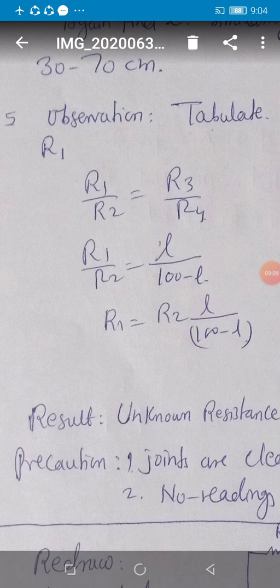Students, some precautions are always taken in an electrical experiment. The current should be switched on only when the readings are taken. And the joints where the wires are joined, any connection, should be thoroughly cleaned, student, because as you know, copper forms oxide, and copper oxide has its own resistance. So the circuit must be thoroughly cleaned at the joint points. Similarly, the null point should be adjusted near the center of the wire, so that the end resistances which are neglected can be cancelled.